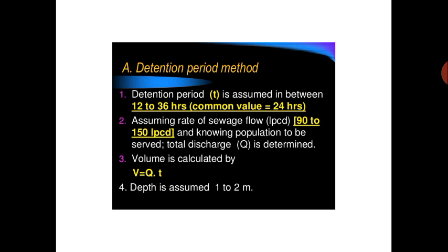So, what are the design details of this septic tank? Detention period is a very important component when we are designing septic tanks, because for the digestion process we have to give sufficient time for the wastewater to contact with the bacteria.